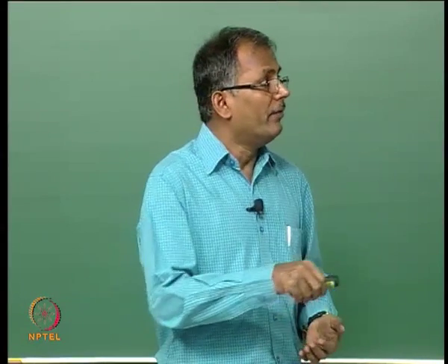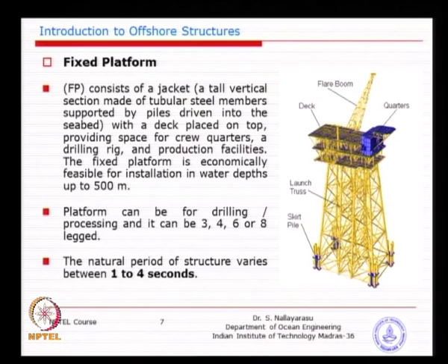So that is why we have such a history of redundant structures with many lattice frames arranged together, so that though it is going to behave like a cantilever, it at least has a spread over a larger area, or the dimension at the base is bigger. And most of the time we use 4 or 8; 3 or 6 is very uncommon. Sometimes, very rarely, we use them. Most of the time we have 4 legs, typically like a tower.